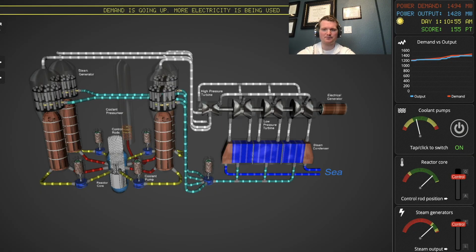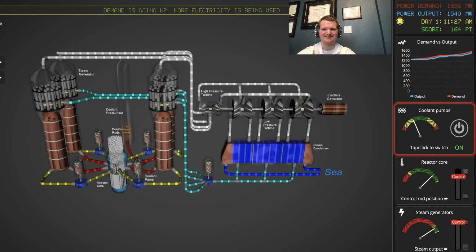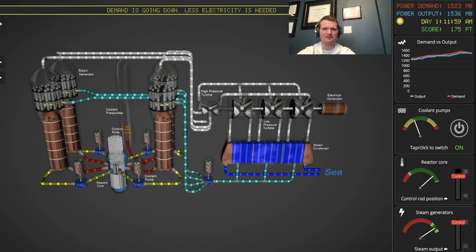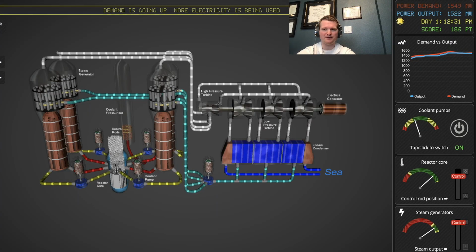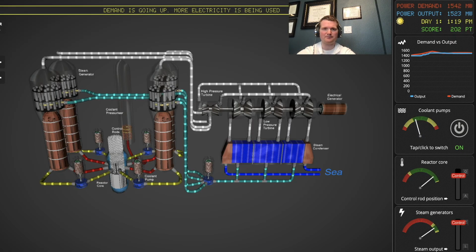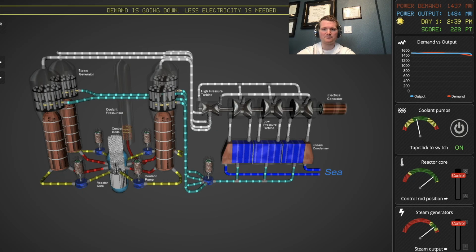But I can see for the purpose of picking three parameters for doing this. By the way, you'd have more than one operator doing this. Obviously, there's a lot more complicated systems at work here. You typically have one operator adjusting control rods, or one on the turbine. Each one would have a peer checker and a supervisor providing oversight. Someone who has a senior reactor operator license, just like the one that I had, providing that.